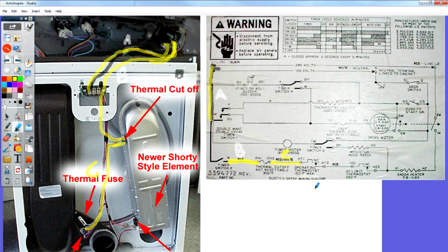Are you guys starting to see how it's pieced together and how the diagram is going? Just a little bit? Yes. Okay, so coming out of that thermostat, where are we going to go? We're right here now on HT3. To the high limit. Okay, where's that at? It's on the right side, at the bottom of the heater. Well, actually, it's on top of the heating element terminals, but it's towards the bottom of the heater box.